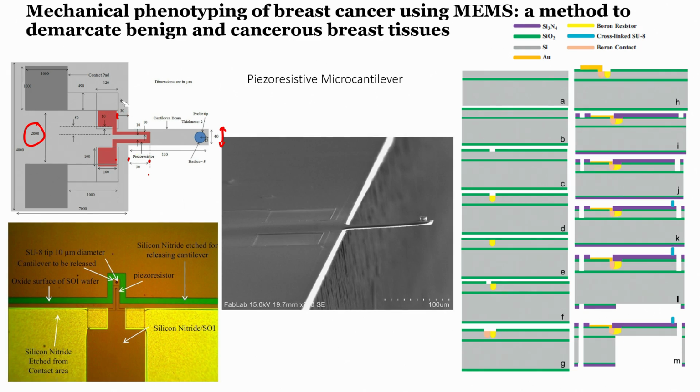Anything else? Yes. So, that is what it is here, and then you have a SU8 tip, which is a probe tip. The radius is about 5, so the diameter is about 10, and I am sorry, the thickness is close to 50 microns. 50 micron is the thickness of the tip. So, you can see here now this tip, this is a SU8 tip, and these two pairs that you see, let us say this is P1, P2.